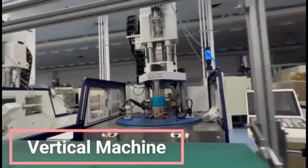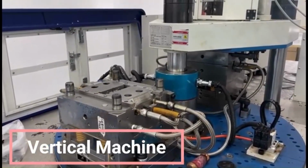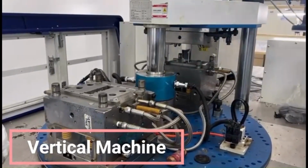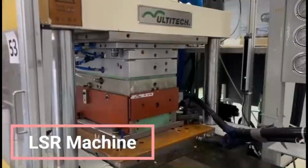A vertical machine refers to a type of machinery where the primary axis of operation is oriented vertically. These machines are commonly used in various manufacturing processes, including injection molding. In vertical machines, the tool or mold is positioned above the workpiece, and the material or part is typically loaded from the top. Next, an LSR machine refers to a liquid silicone rubber injection molding machine.